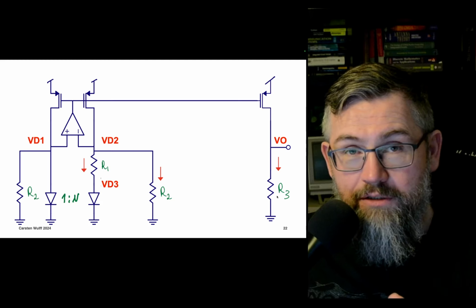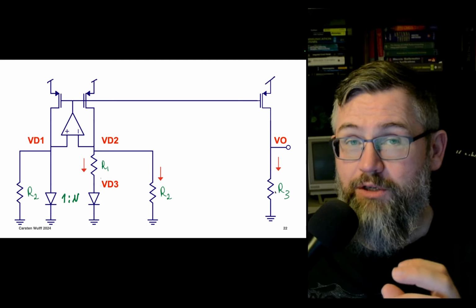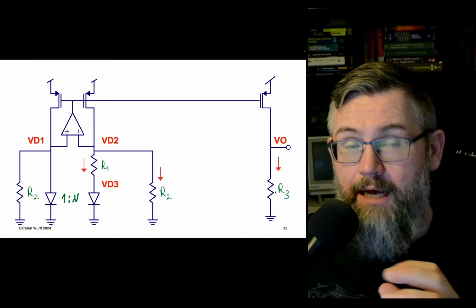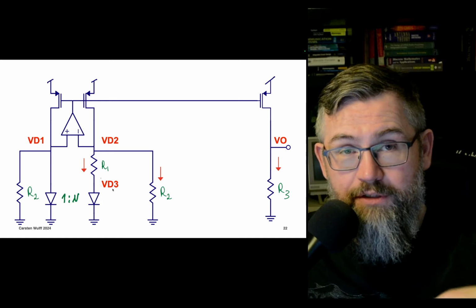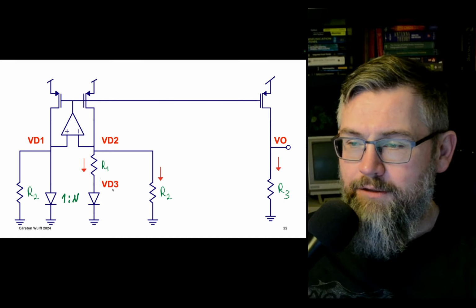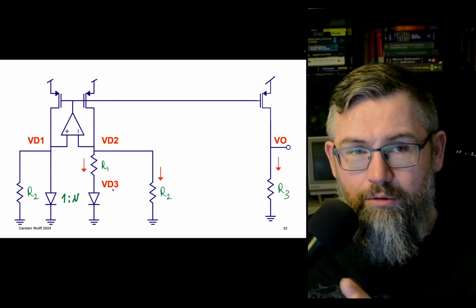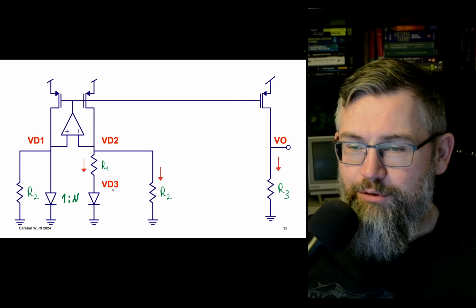if you put the equations up, you will figure out that the output voltage actually depends on relationships between resistors. And as long as all the resistors increase or decrease with the same type of coefficient, the relationship between them will stay the same. So that's usually not a problem. So the bandgap reference, you can read the original paper.